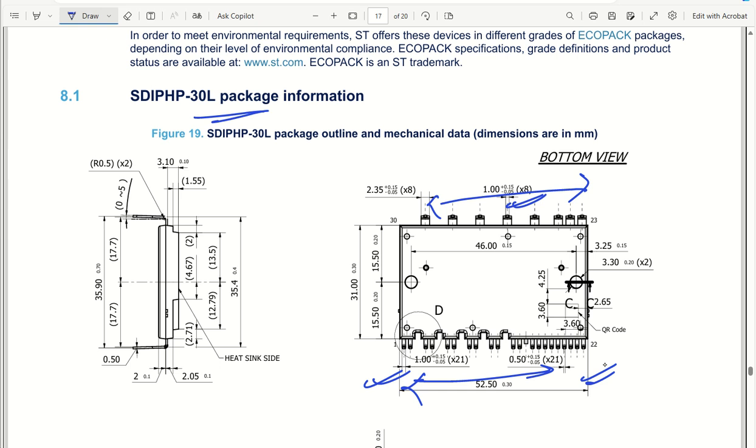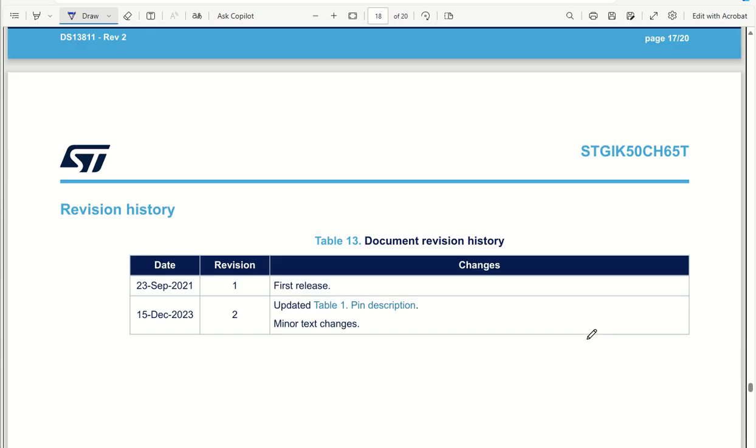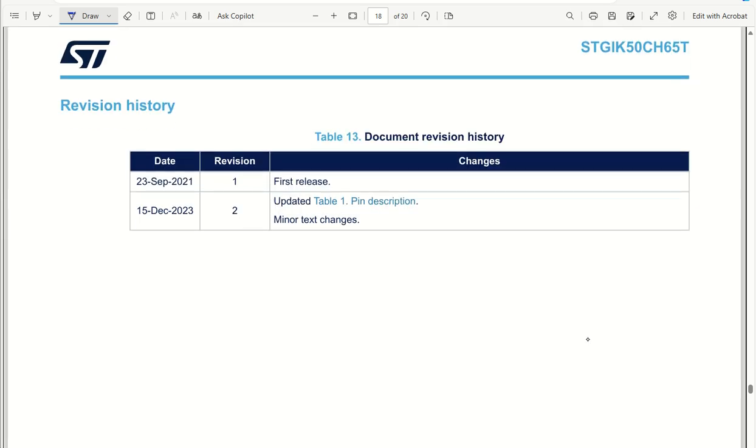These are going to get the 400 volt inputs and then drive the U phase, V phase and W phase, and these will be the NU, NV and NW pins. That's the reason they need a higher pitch, so that we can have proper heat dissipation and thermal capabilities.